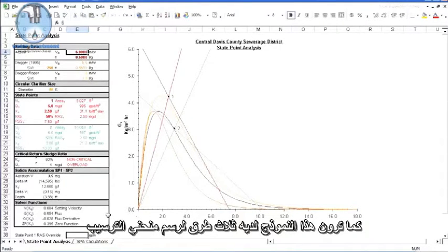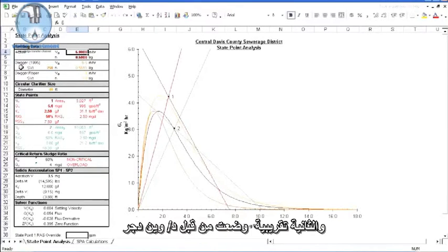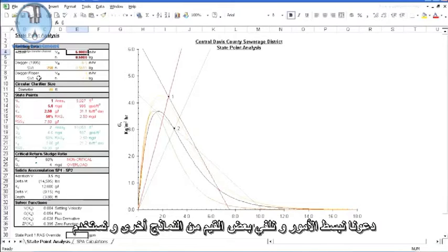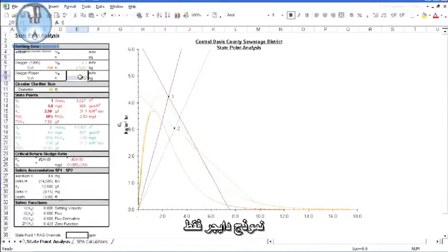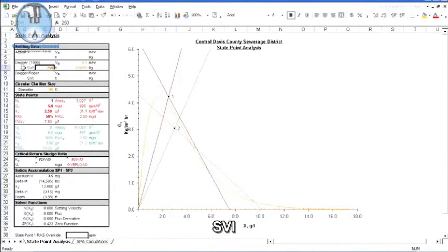As you can see, this model has three methods for developing settling curves. The first is based on actual measured clarifier characteristics. The second is an approximation developed by Dr. Glen Daigger. The third is a modification on the Daigger model called the Daigger-Roper. Let's simplify things and clear some values out of the other models and use just the Daigger model only.